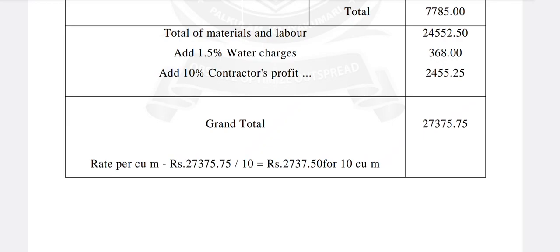Labor requirement: mistry or head mason, 1.5 numbers, at 350 per day. Mason, 1.50 numbers, at 300 per day. Mazdoor, 12 numbers, at 220 per day. Boy or woman coolie, 18 numbers, at 200 per day. Bhisti, 4 numbers, at 200 per day. Sundries, lump sum, 120 per LS.